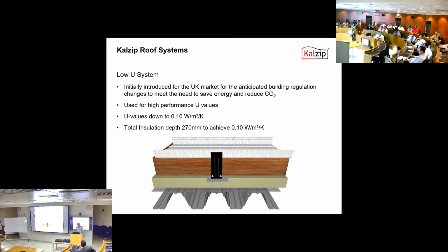This is a system we've introduced maybe 10 years ago. It's a hybrid system to achieve low U value performance. You see U values down to 0.1. I think normally U values in this region you're looking maybe 0.18 sort of U value. So it's a hybrid, it's a mix of PIR board and glass fibre insulation. So it's very, very energy efficient and reducing your carbon emissions. We have design tools again, so we can work out different U value performance by mixing and matching this thickness of insulation and this thickness of insulation, so we can look for the optimum performance.